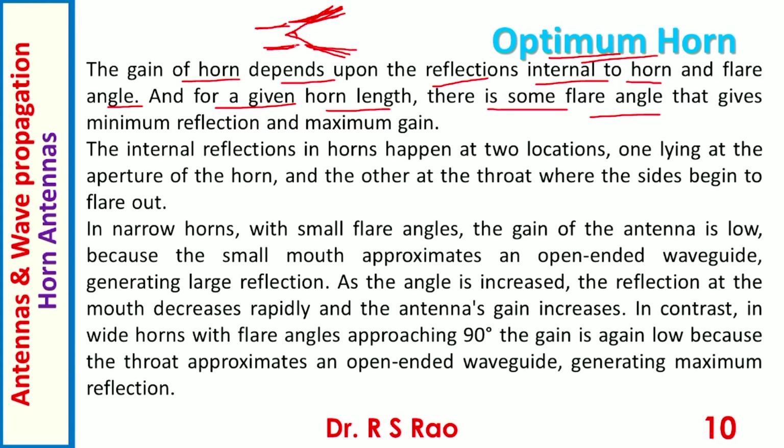One point requires to be mentioned here: the purpose of a flare, as already mentioned, is to increase the gain of the antenna. If a flare is not there, gain is almost nil. You don't find any gain from the simple waveguide. So opening out is done to have more gain.